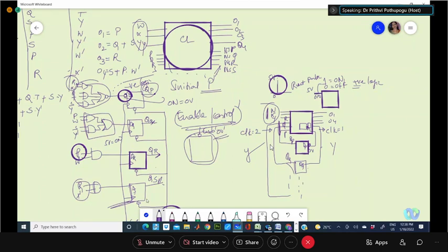So this is a continuous process. There won't be any stopping there. Where do you stop? Once you initialize that your design starts from P, there will always be one condition true, no? Any place you take, there will be one condition that will be true always. That means the transition will be between P, Q, R, S based on the paths you are defining. These are the paths you are defining.